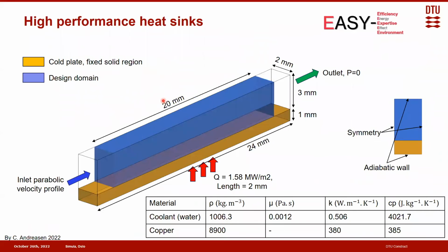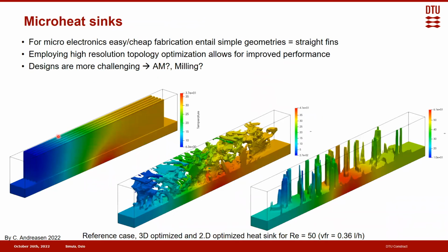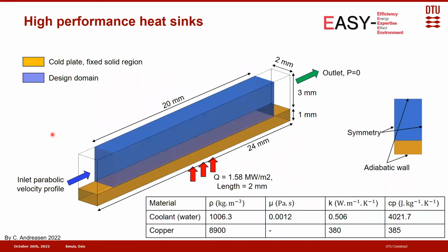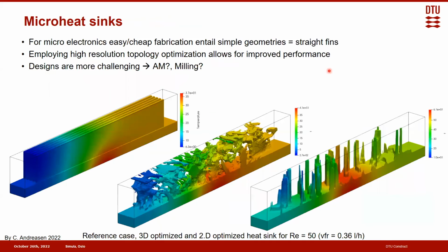And something that's more industrially relevant, heat exchangers. So this is a heat sink. It's easier to see here. This is a part of a parallel plate heat sink for a chip. But here you have a strong convection, meaning that you have a flow. Where is my drawing? Here. You have a flow of cold air coming in, heat from here, and an outlet. And of course, again, we are at the microscale, meaning that we are not going into high Reynolds number flows.